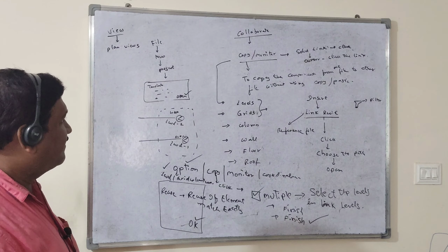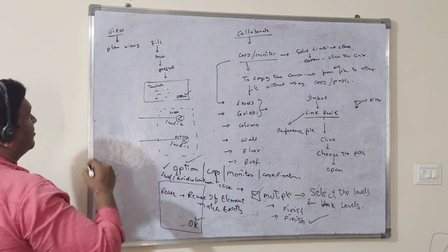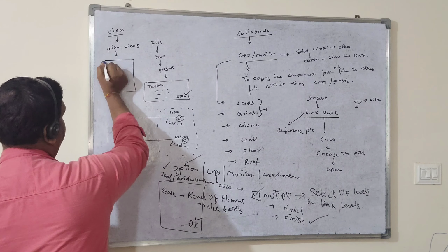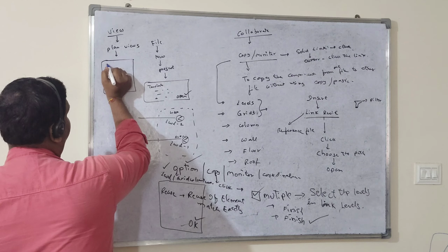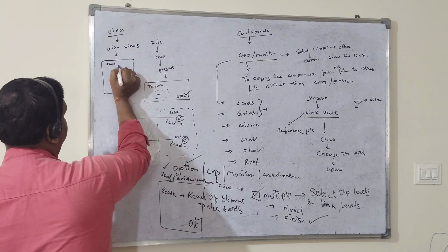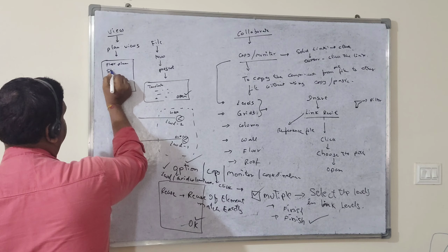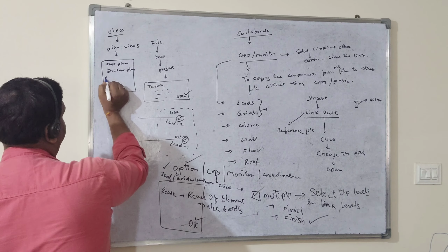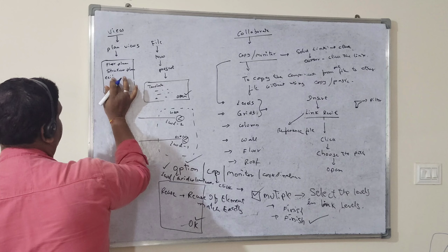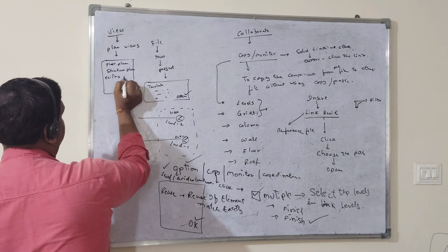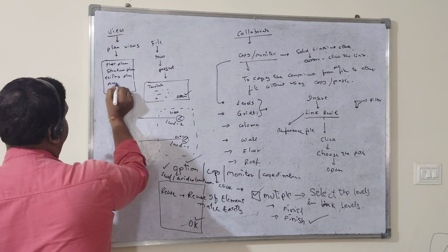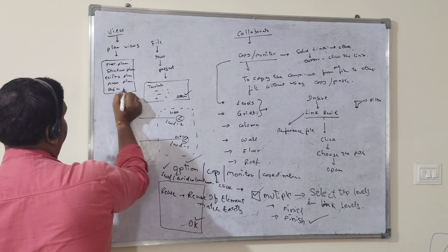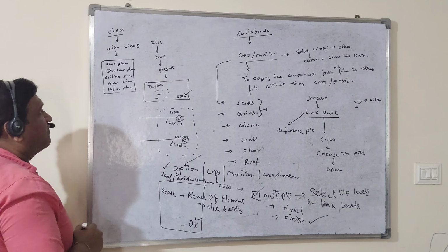Plan views. Plan views will be there in the view menu. If you click that plan views, again a palette will come up like that. In this palette you will find a floor plan, a structural plan, a ceiling plan, an area plan, and one more plan, the region plan. Like that you will find there is a flag.